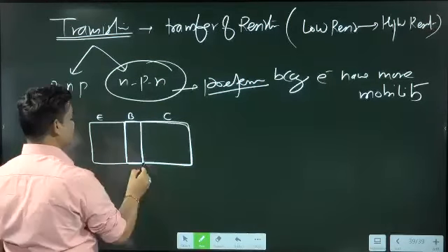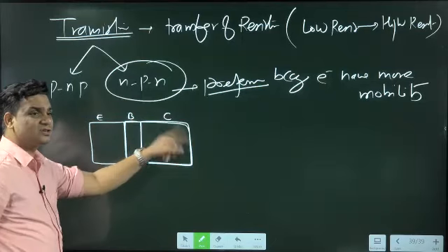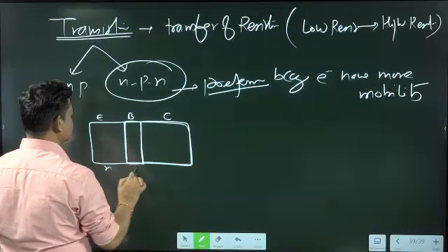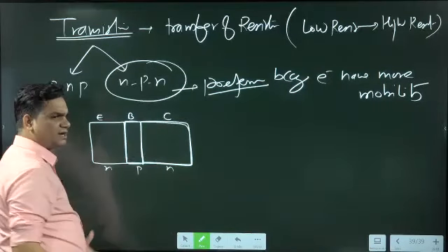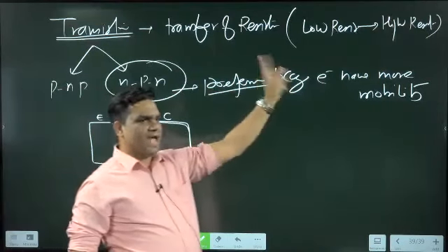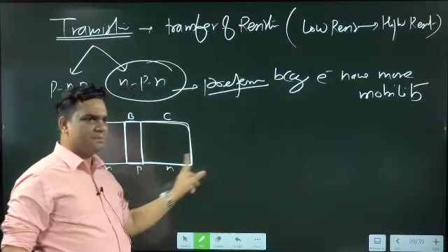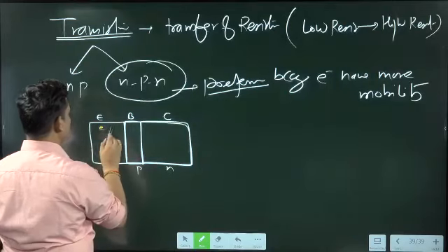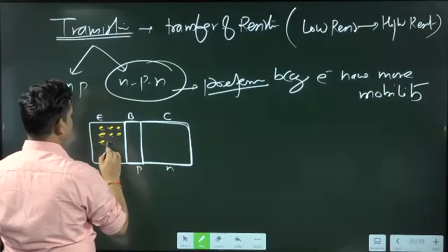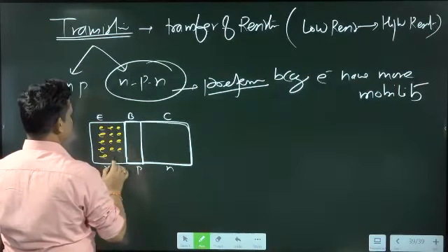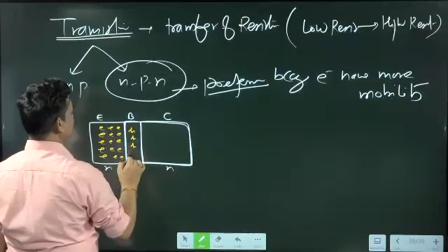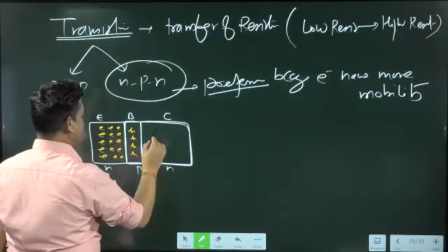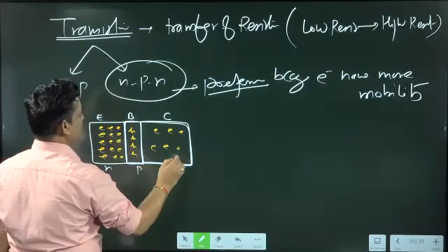Base is always least. A lot of time I have asked this question: why is the base least? What will be the possible reason? Take the NPN example here; you can take NPN or PNP, but we are going to prefer NPN, so I will always write NPN in the examples. In NPN we have a huge number of electrons, and in P you will have holes as the majority. I am only drawing the majority carriers because they are mainly responsible for the current.